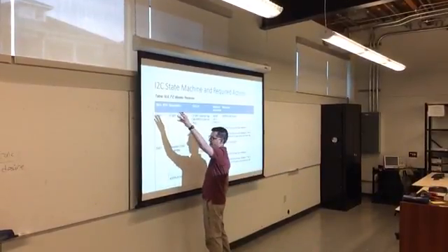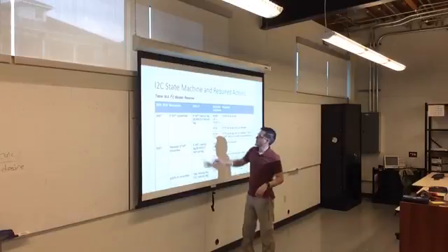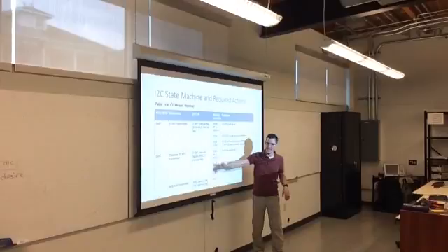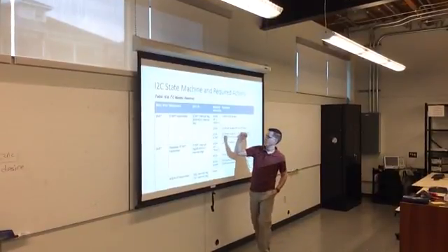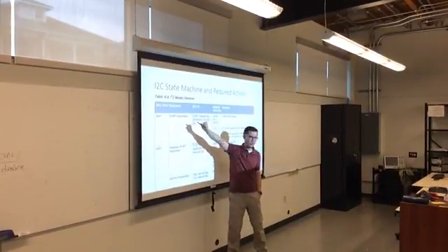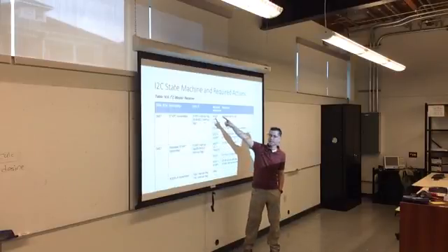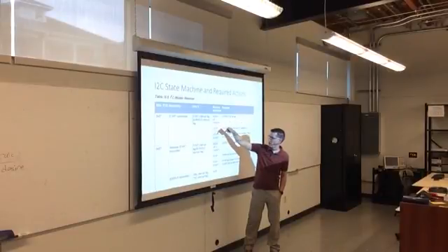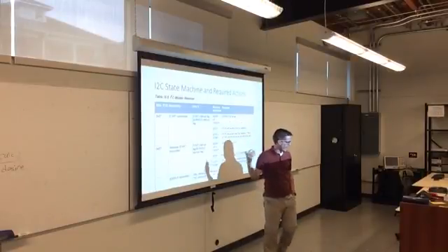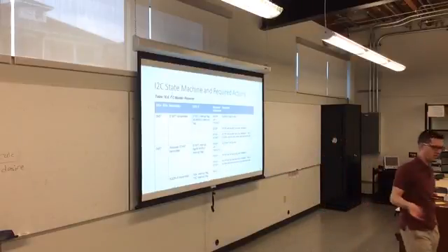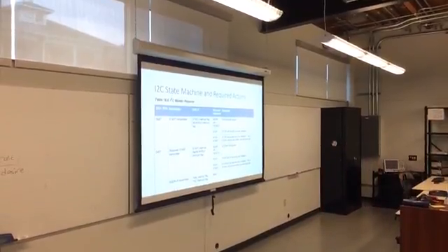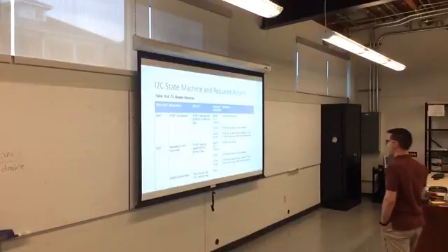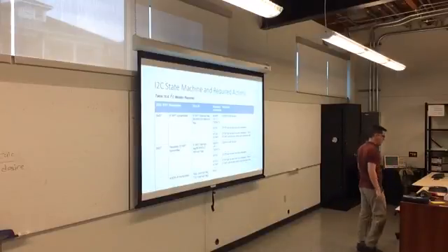So if you've just sent a start bit, you can send an address with a read packet. You can send a stop bit. You can send a start bit, then a stop bit. It tells you a list of things that you can possibly do once you're in that state. This is way more information than you need. You really only need to follow that graphical diagram. And this is only for the master receiver chart. So this is that second state machine turned into a table.